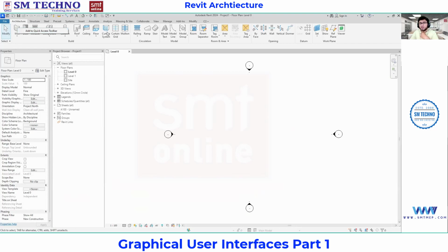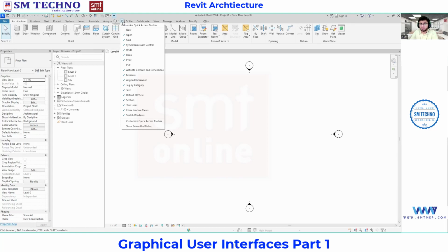It's very simple. Whichever option you want to select, it will be in the quick access toolbar, right? I'll right click from here, add to quick access toolbar. So it doesn't mean that the option will go from here. It will also be there. Along with this, you're going to find it in the quick access toolbar also, like when you just customize this, you'll be finding the same option.